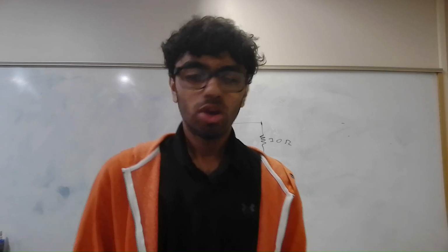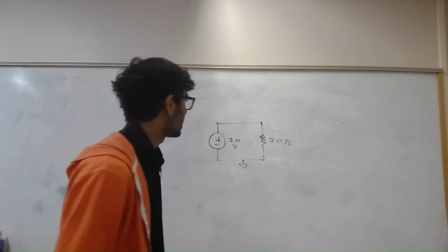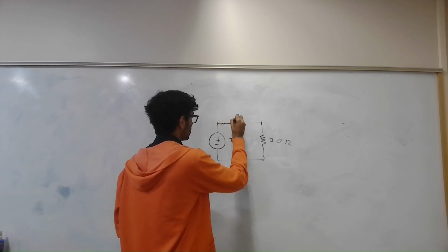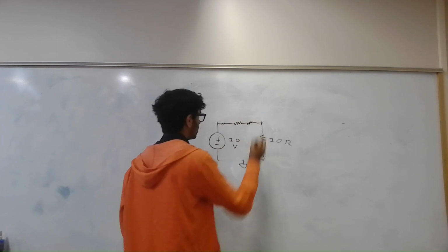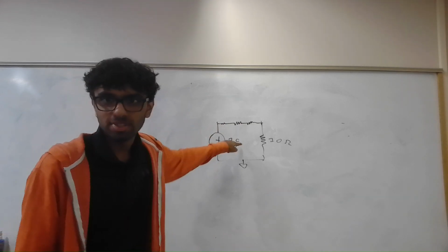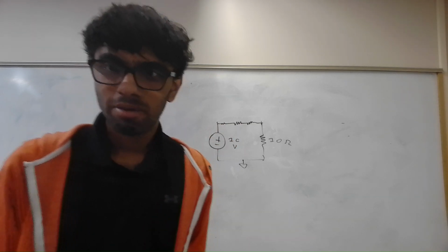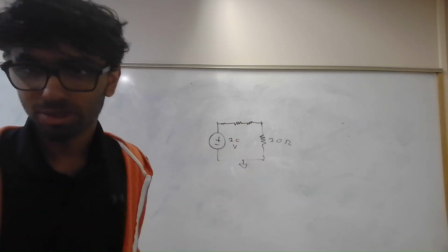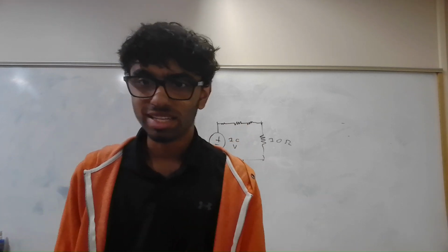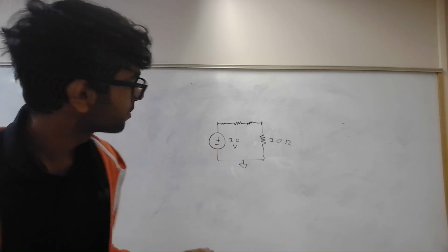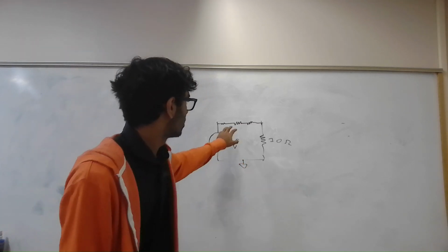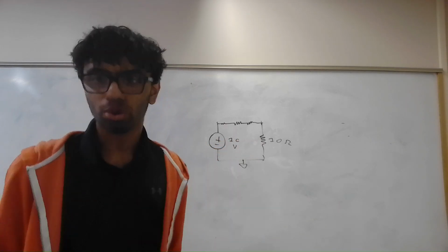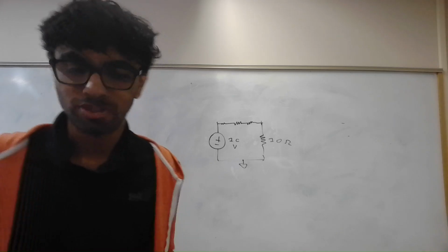Okay? What we noticed when we attach multiple resistors like this is we're adding their resistances. You may have seen this by the fact that the same current has to flow through all of them, and as we'll do next class, we'll derive what that means for how to simplify that circuit. But if we attach all these resistors in series like that, we increase the total resistance. We're having a more resistive circuit, right?